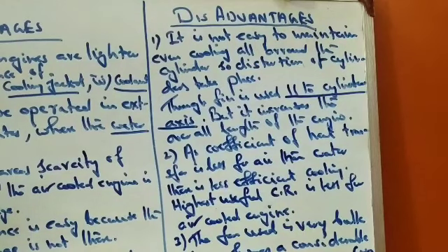So the efficiency of air cooling system inevitably becomes lower, and the highest useful compression ratio, CR meaning compression ratio, has to be lower for air cooled engines, because if you use a higher compression ratio, a higher amount of heat is produced. So you have no options to dissipate the heat.